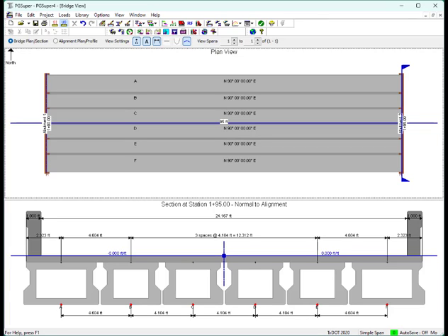The available options for girder spacing are different for each beam type. For example, adjacent spacing probably never makes sense for I-beams, so that option is not supported. I've chosen a box beam bridge here because I think of box beams as the Swiss Army knife of spacing options. Box beams support almost all of PGSuper's available spacing options, except for the adjustable flange width options found on some decked girders.